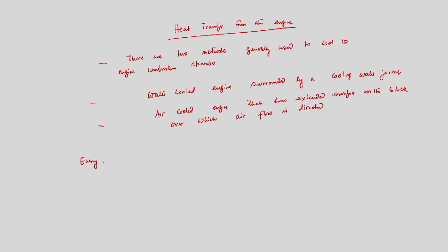Now, if we talk about energy distribution, this is very important. So, what is energy distribution? We have seen that the total power generated will be some amount of W dot shaft work plus Q dot loss plus Q dot exhaust, because some amount of energy is leaving with the exhaust, plus W dot accessories.